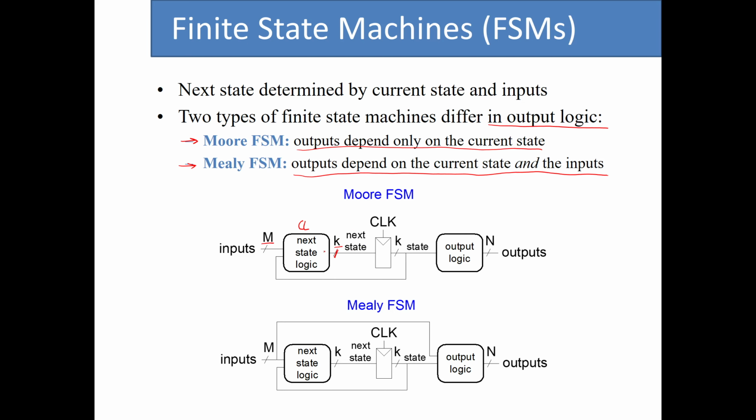So these K outputs coming out of this combinational logic circuit will be fed to a bunch of registers or flip-flops. At the edge of the clock, signified with this triangle, they will be stored in the flip-flops. So now we said that for the sequential circuit, the state of the system not only depends on the input at the current time, but the previous state. So that's why we have this feedback path that connects the output of the flip-flops to the input of this combinational logic that we use for calculating the next state. So that is the feedback path that we have. And if you look closely, for this cyclic path, we have registers in the path. So that makes this circuit to be considered as a synchronous sequential logic circuit, not an asynchronous.